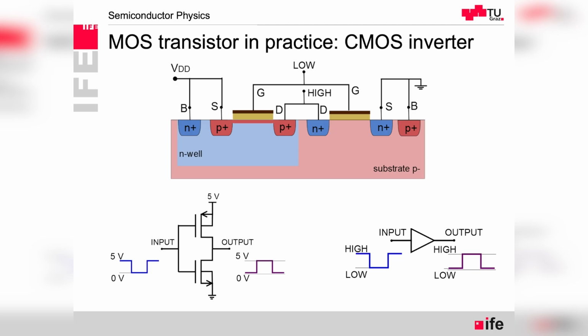We want to use the smallest size transistors to have low capacitance. On the other hand, we want low on resistance, so maybe we use the minimum, or extend the width of the transistor and use the minimum channel length so as to reduce the on resistance.